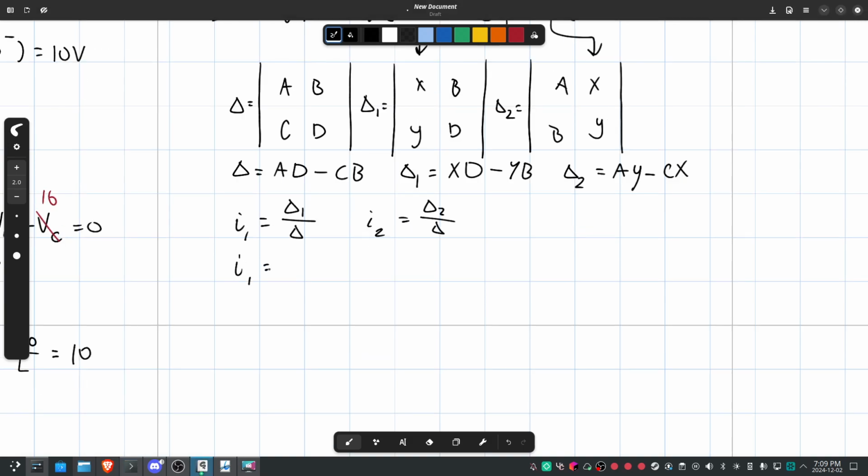So I1 is just 10. And then I2 is -6 minus 8j. So that's 10 with a phasor of 0. This is, what is that, -6. The only problem with MATLAB or GNU Octave, whichever you use, is that it doesn't accept phasors. You can only work in rect, which is a little annoying. Anyway, this is 10 with a phasor of -127, if I put the numbers right in MATLAB, and I believe I did.